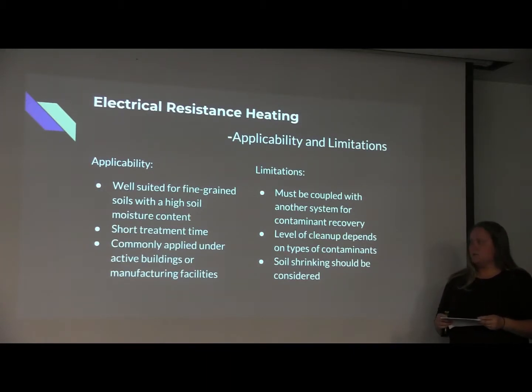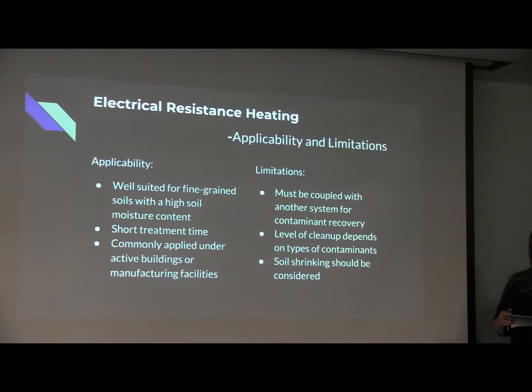Some limitations: the heating remediations do not recover the contaminants, so they must be coupled with another system for full contaminant recovery. The level of cleanup depends on the types of contaminant present at the site, but soil shrinkage should be considered under certain geological conditions.